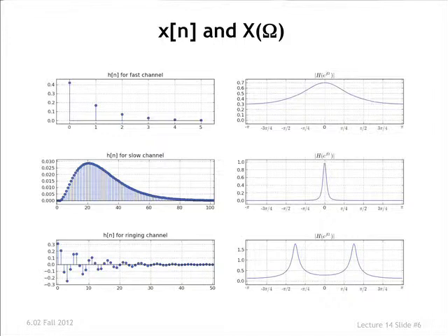Okay, so where is the spectral content concentrated? Is it at low frequencies or high frequencies or intermediate frequencies for this first example? Concentrated around 0, so you'd say it's concentrated at low frequencies. There is content at all frequencies, though, so this doesn't dip down to 0 anywhere else. You have to assemble a combination of sinusoids at all frequencies to construct this signal here.